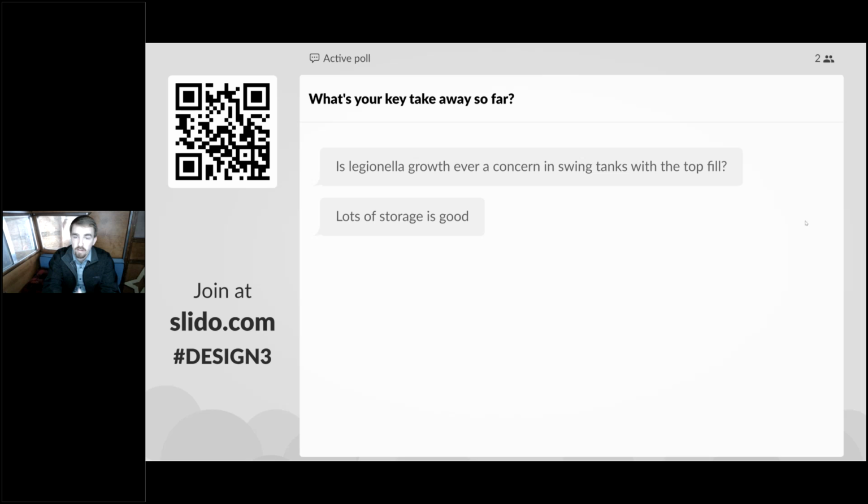And if you're seeing a control sequence and you're seeing the heat pumps turning on at 120 or maybe even 100 degrees, that doesn't mean that the water temperature above that sensor is going to be 120 degrees when it turns on. That just means that the tank has filled with cool water up to the point of that sensor location before it turns on. So yeah, great question. And sorry, was there a second part of that question that I might not have addressed?